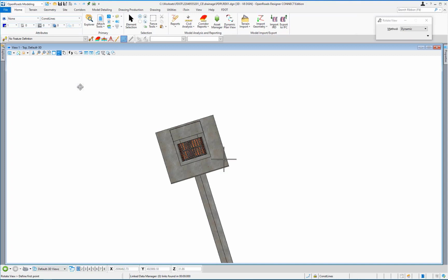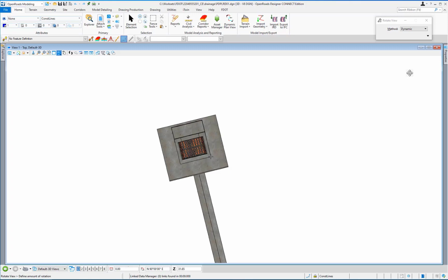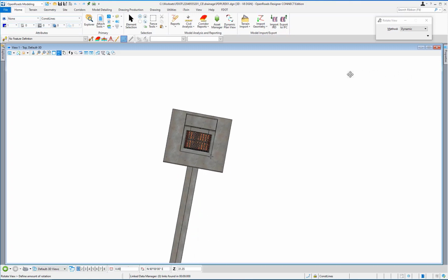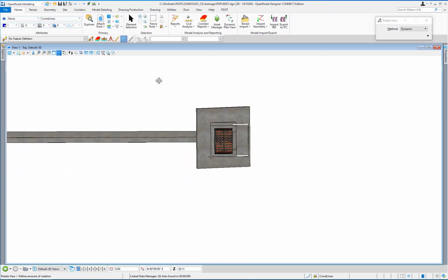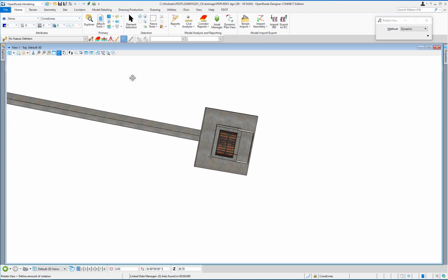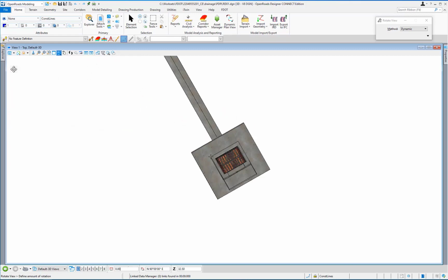Left-click on the white View Rotation cross and move it to the lower right corner of the top of the structure. Once it is snapped to the lower right corner of the structure, left-click to accept the new location. Move the cursor off the structure to the upper right and left-click to begin rotation. Bring the cursor across the view to the left until the pipe is at somewhere near a 45-degree angle to the left of the structure and left-click to accept the rotation.